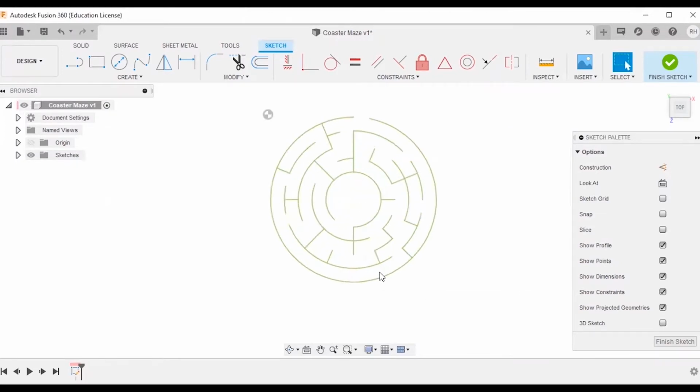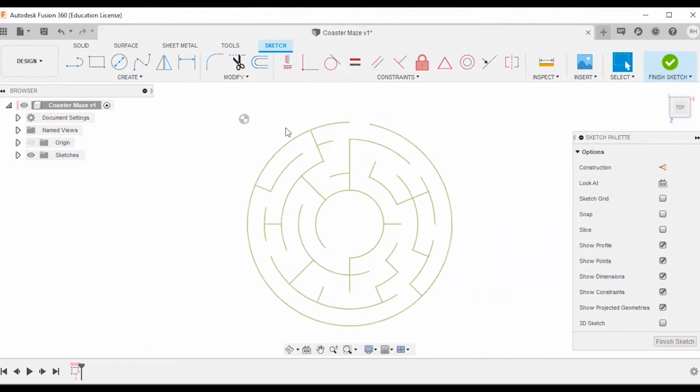Zoom in here. Now the SVG comes in as a green colored line segment, and that means that all these elements are fixed. So we're going to unfix them by selecting the lock icon, and we'll drag a window around everything, and then escape to get out of the lock tool.